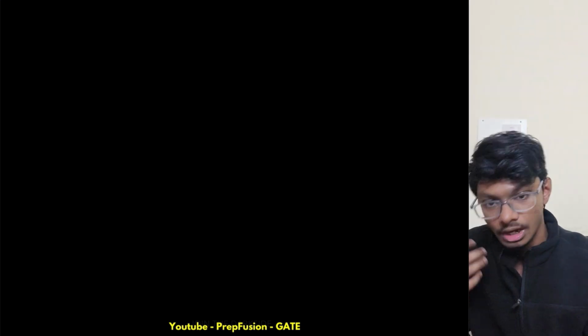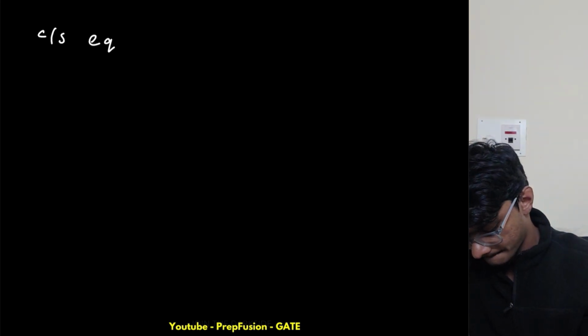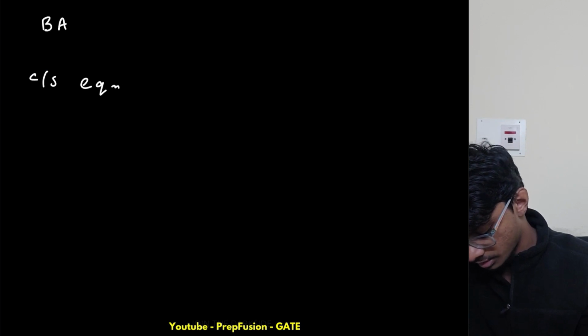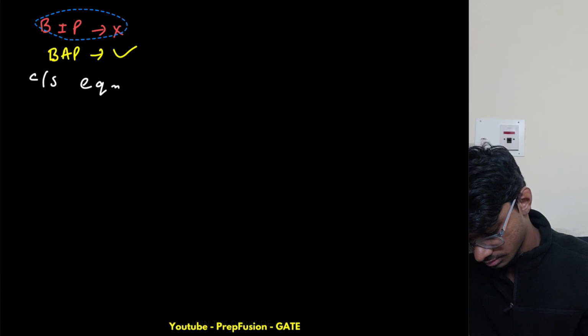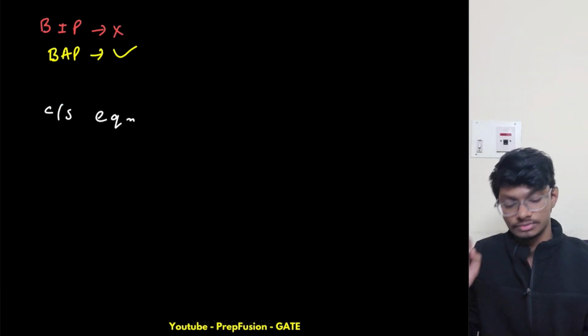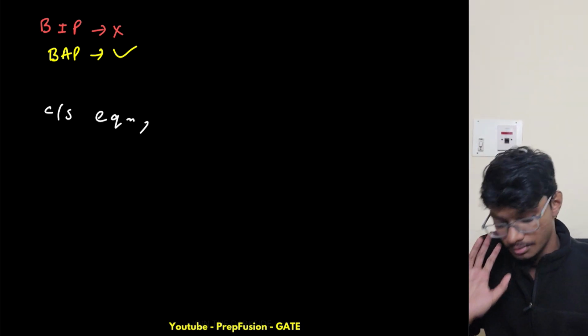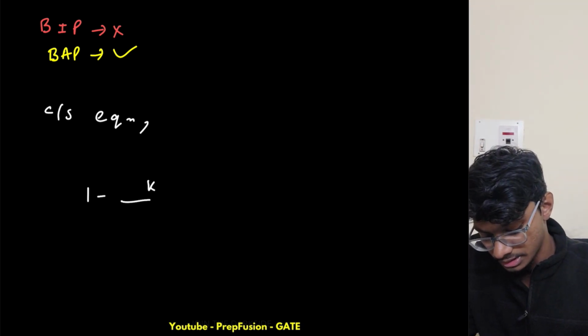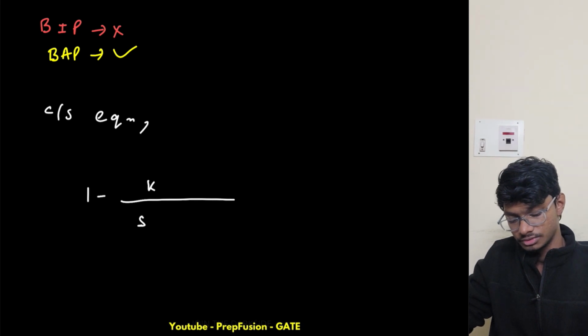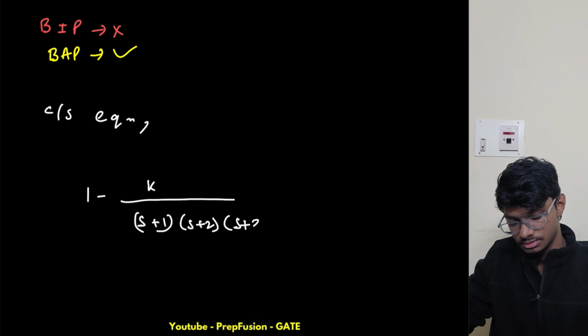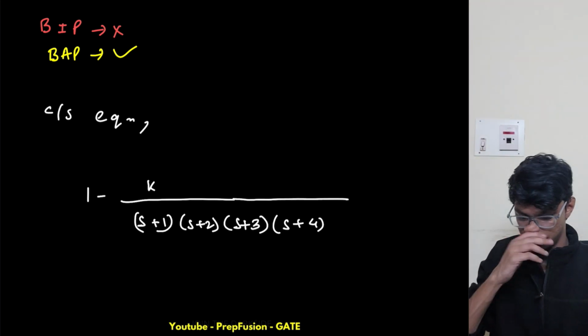Basically, I will have to solve the characteristic equation. So I will write here: no break away, no break in point. I will get a break away point. Okay, so this one with color red. Now what we should do is write the characteristic equation. I haven't written it down yet, so this should be minus. I hope you understand why this is minus. Basically the characteristic equation will be minus s plus 1, s plus 2, into s plus 3, into s plus 4, equals 0.